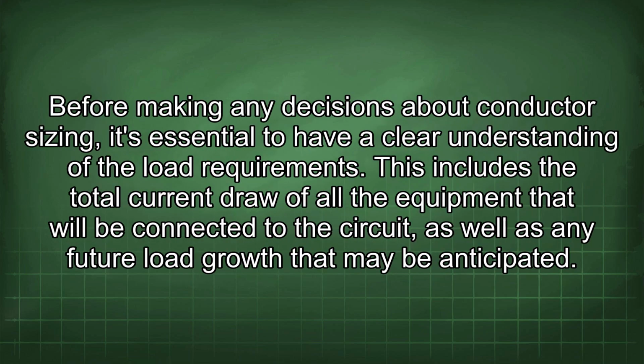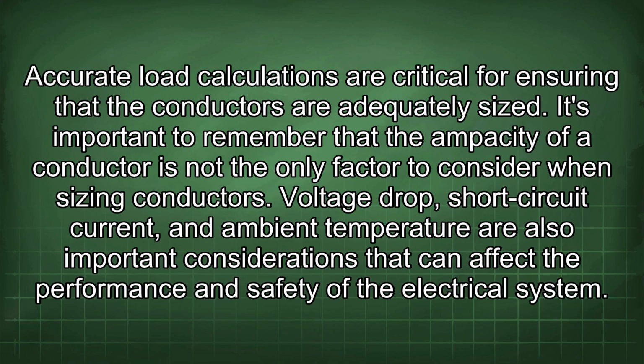Before making any decisions about conductor sizing, it's essential to have a clear understanding of the load requirements. This includes the total current draw of all the equipment that will be connected to the circuit, as well as any future load growth that may be anticipated. Accurate load calculations are critical for ensuring that the conductors are adequately sized.